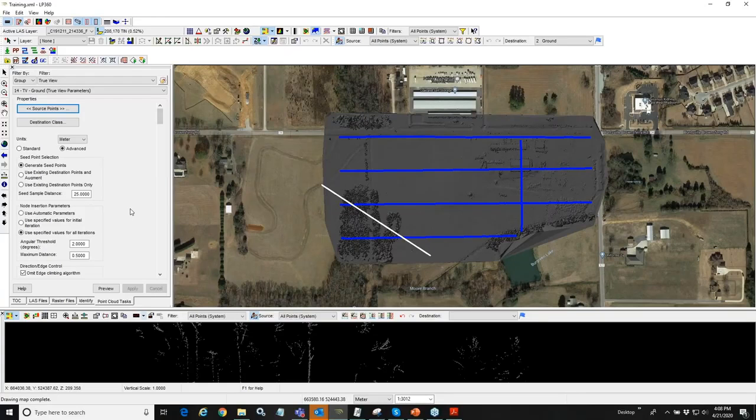Having configured the point cloud task, I would go run it. Typically, I would run against the whole data set, the whole project. You can run it just in certain areas. You can run it against certain boundaries, polygons, if you have certain areas that you want to run. Again, a lot of power there that we get more into in the training. This particular ground classification for this data set takes about 2.5 minutes to run.